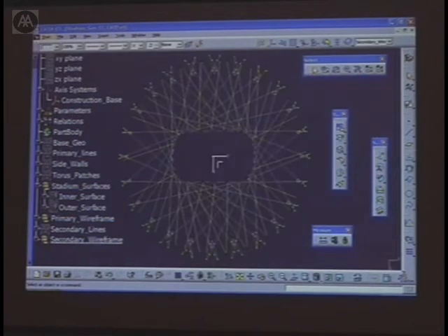The project, for those of you who know it, is actually not a chaotic project. There's actually some method to the madness, in the sense that it's a very large, very round ellipse, but it is nonetheless an ellipse. You have these 24 gables that reside around the perimeter of the project, out of which you lay tangents to this interior oval. You take the bisectors of those tangents to draw another line, and that's how you get this. So in fact, the stadium is actually rotationally symmetrical, meaning that this side is exactly the same as that side, and at least you get a number of 2 for every component that you want to build.